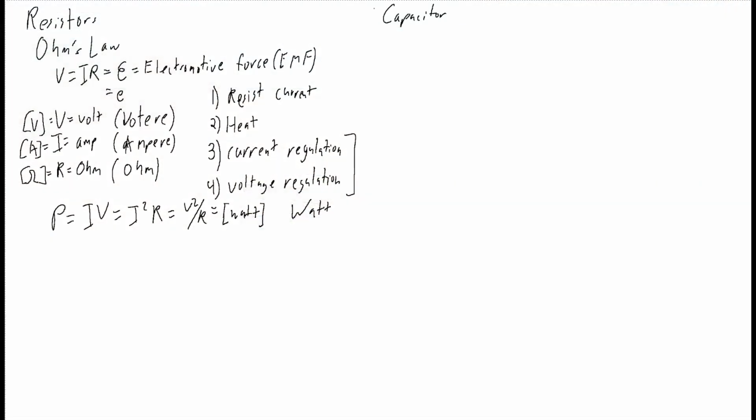So the first 2 digits are going to be the significant figures, 2 sig figs of the capacitance, and then the last one is the power on the capacitance. So if I flip over to the capacitor, 106, right?